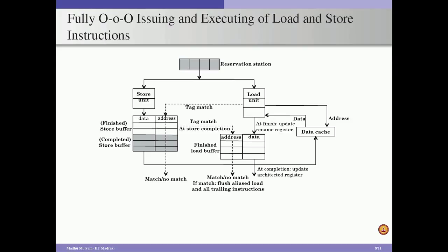We have store instructions, store X and load Y. This load instruction is coming after the store instruction, and because this load instruction is independent of the store instruction, we can execute this load instruction in out of order fashion. In such a scenario, while the store instruction is issued to the store unit, we issue the load instruction to the load unit.